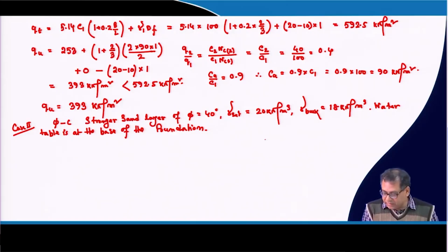Before I go to the calculation here, you cannot use the basic equation that I have given directly, because here you have to do some slight modification. In earth pressure there is only gamma 1 term, but now the gamma will be different, because water table is present. So, let us first calculate the earth pressure, then we will put that value in your equation. I will show you how we can calculate the earth pressure.